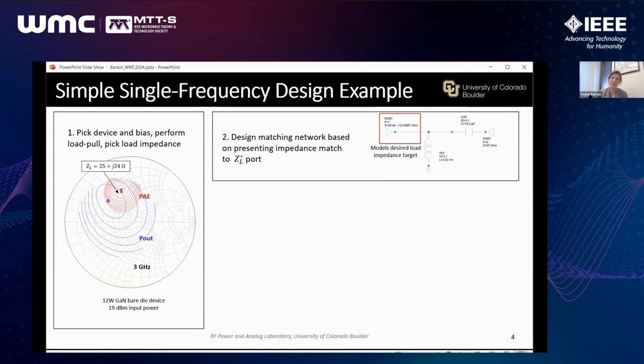First of all, why would I want to do it this way with a port instead of using the large signal model? You'll see in a lot of our designs, we use a small signal approximation to the large signal model, which seems very roundabout, right? The load pull itself is clearly a large signal simulation, right? It's in compression. If this were a small signal, then our output power and PAE optima would be aligned. So we need the large signal model. Power amplifiers are nonlinear. Can't model it with S parameters. But at the same time, in the simulator, and especially in MMIC design, we rely a lot on EM simulation and optimizers.